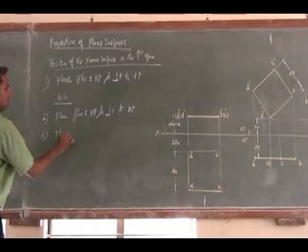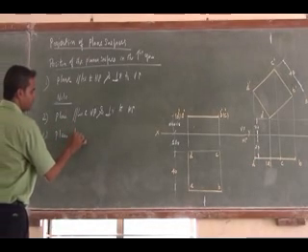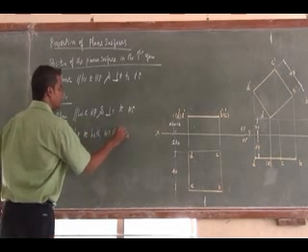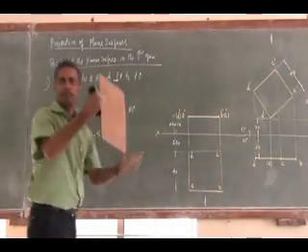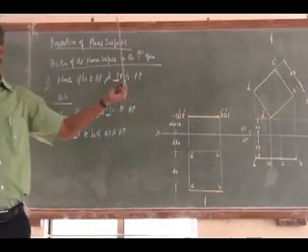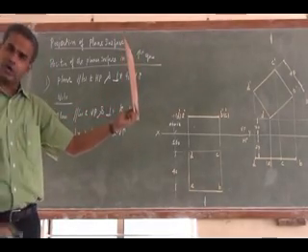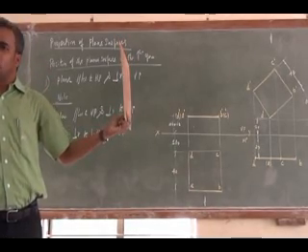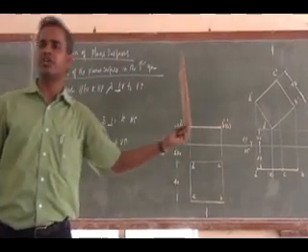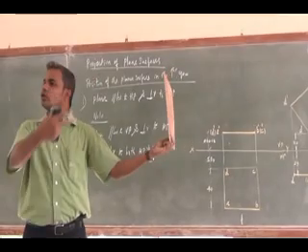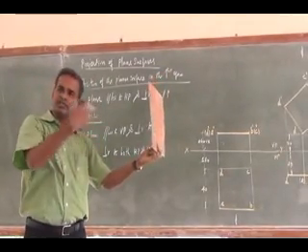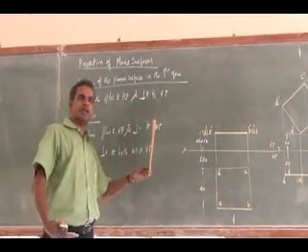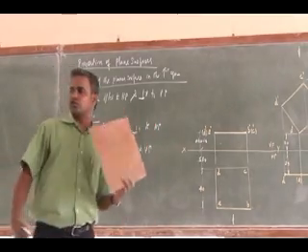Plane is perpendicular to both HP and VP. What is this orientation? We have a plane like this. So it is perpendicular to VP and it is perpendicular to HP. So where will I obtain my true shape in this orientation? True shape will be on the right side, not the front view, since it is perpendicular to HP and perpendicular to VP. As you know, wherever it is perpendicular, I will obtain a straight line as a view. Okay, in both views I will obtain a straight line.